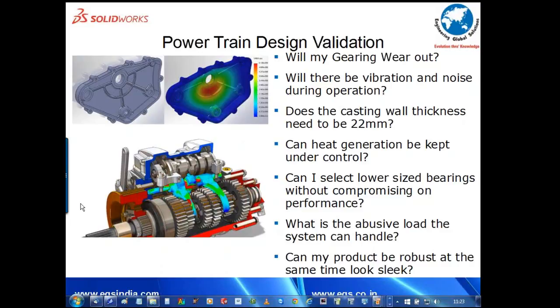So what you have to give to the customer is, for operating load, a certain mean time between failure. You put that on your service manual explicitly and in your warranty conditions which the customer signs across and accepts. Then you give the limit load on the model, on the product that you have designed.